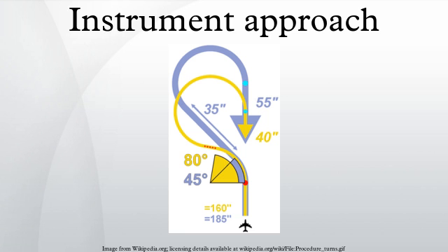landing. It is a maneuver used when a runway is not aligned within 30 degrees of the final approach course of the instrument approach procedure, or the final approach requires 400 feet of descent per nautical mile, and therefore requires some visual maneuvering of the aircraft in the vicinity of the airport after the instrument portion of the approach is completed to align the aircraft with the runway for landing.